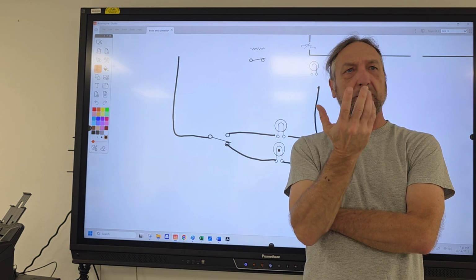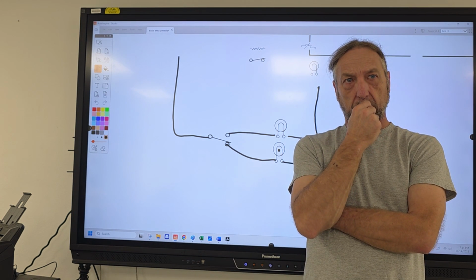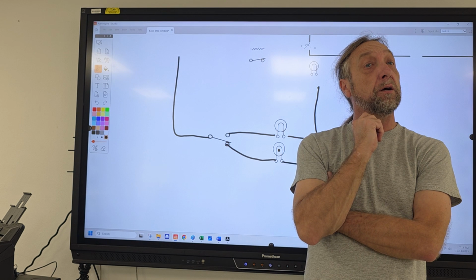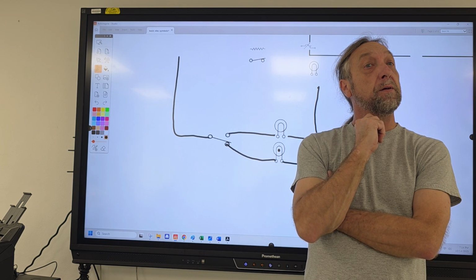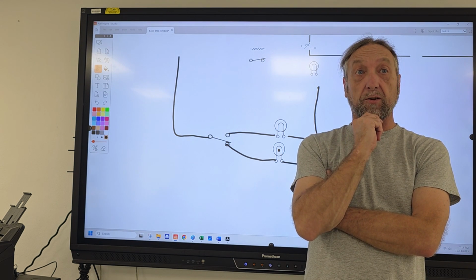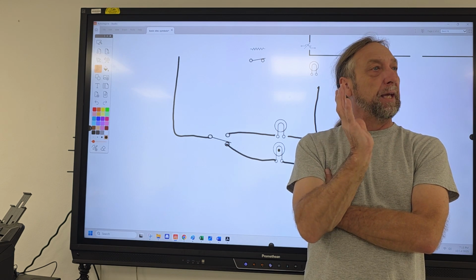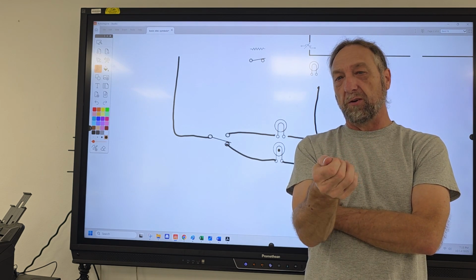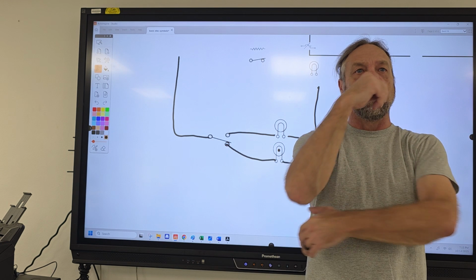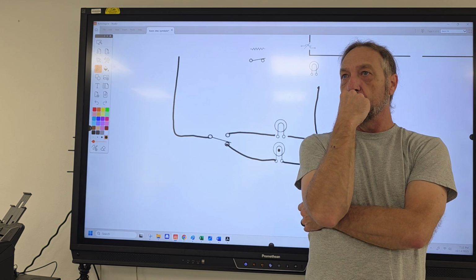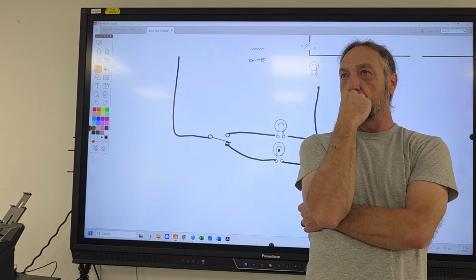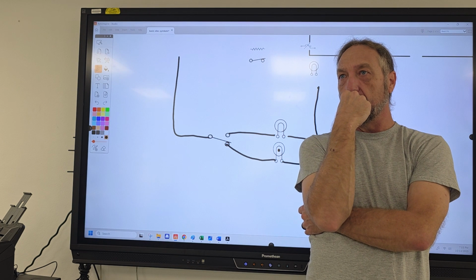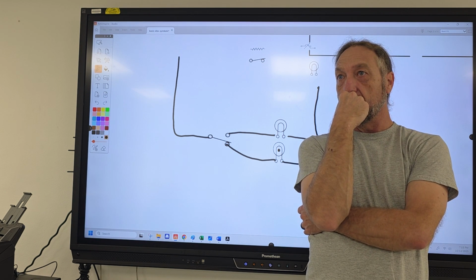What's our next step before I tell you what I did? Self-clean cycle. That's where I put it on bake, it worked. I put it in broil, worked. As soon as I put it in self-clean, boom, blew up the highest thermostat. So y'all look at the thermostat. Maybe thermostat's what blew up. Oh, that's what blew up, then I'll call my supervisor.